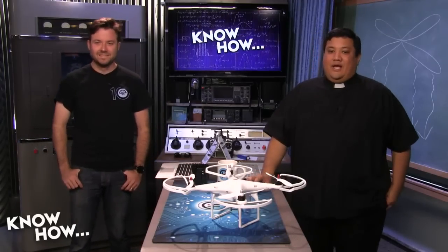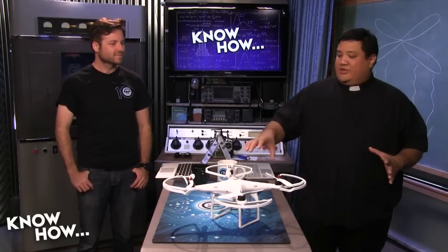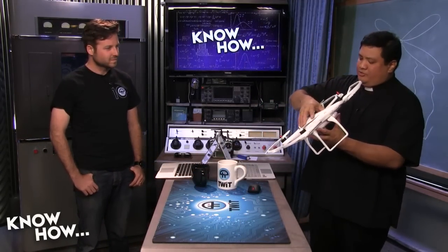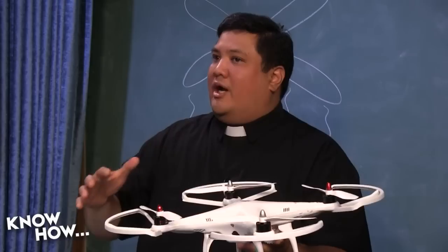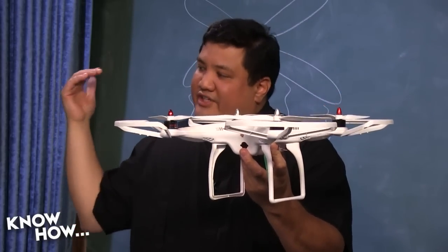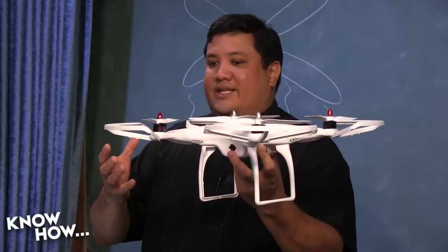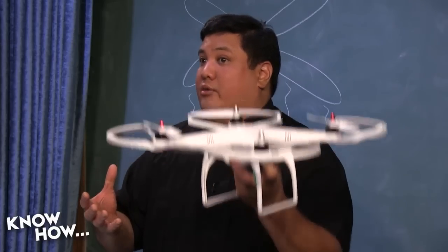That's not good. Yeah. Now, there's a couple other things that we do want to talk about with rotary wing craft, because we've had quite a few questions about, why does my quadcopter fly strange? Why is it that I have it hovering and it gets hit by a breeze and suddenly it starts rising all on its own? Right. Well, you just have to look at the aerodynamics of a rotary wing craft. This is essentially a huge sail area. When these props are spinning, even if it's stationary, if it gets hit by a gust of wind, it's going to treat it like a sail, and that sail could just make it rise. It will rise on a gust of wind. It will drop on a gust of wind.